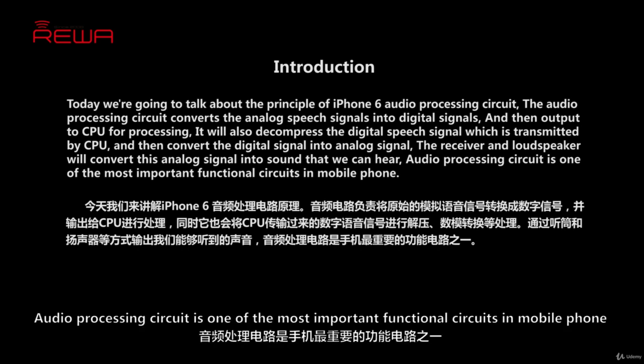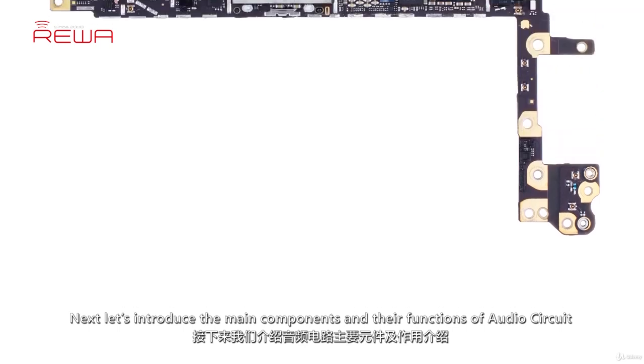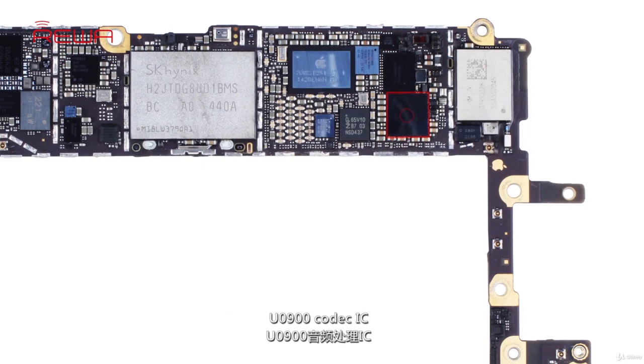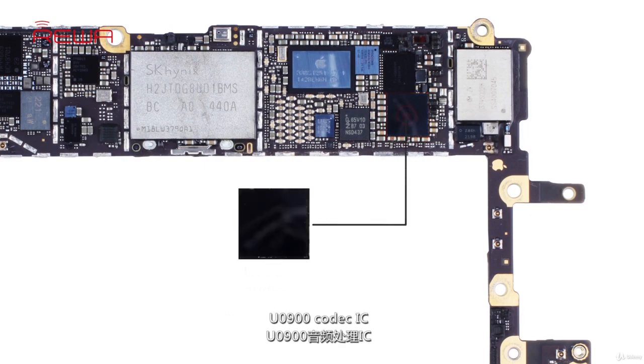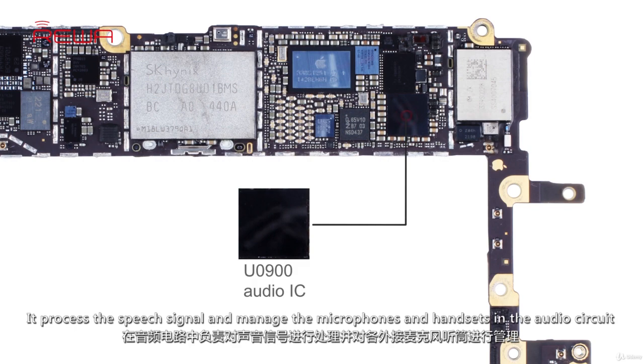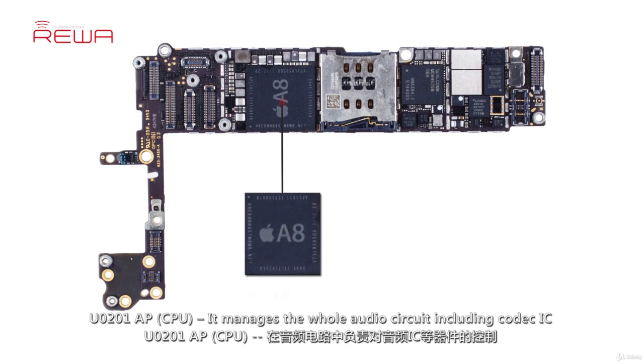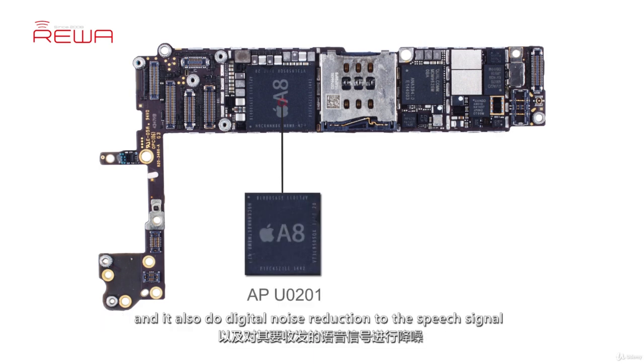Audio processing circuit is one of the most important function circuits in mobile phone. Next, let's introduce the main components and their functions of audio circuit. U0900 codec IC. It processes the speech signal and manages the microphone and handsets in the audio circuit. U0201 AP CPU. It manages the whole audio circuit including codec IC, and it also does digital noise reduction to the speech signal.